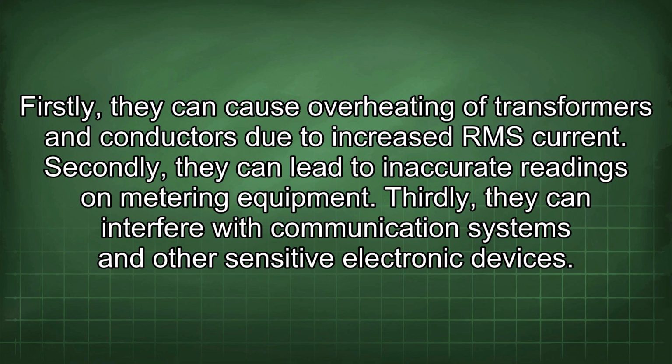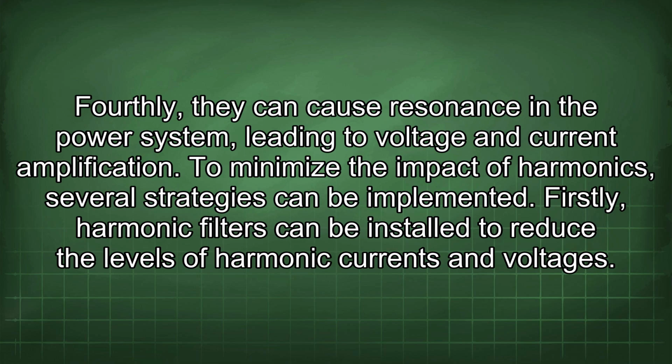Firstly, they can cause overheating of transformers and conductors due to increased RMS current. Secondly, they can lead to inaccurate readings on metering equipment. Thirdly, they can interfere with communication systems and other sensitive electronic devices. Fourthly, they can cause resonance in the power system, leading to voltage and current amplification.